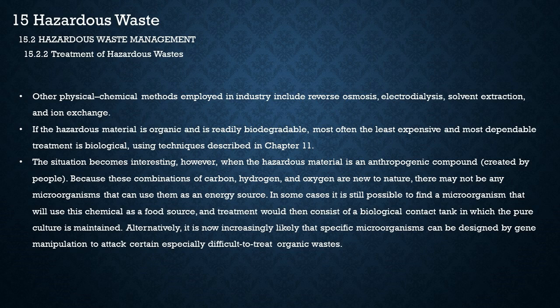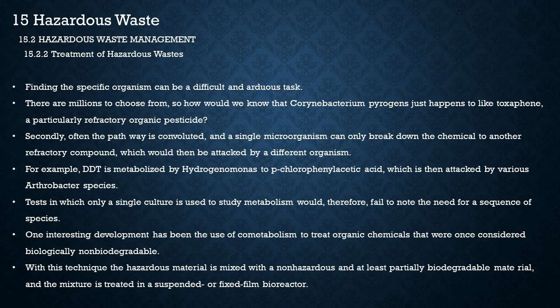The situation becomes interesting, however, when the hazardous material is an anthropogenic compound created by people. Because these combinations of carbon, hydrogen, and oxygen are new to nature, there may not be any microorganisms that can use them as an energy source. In some cases, it is still possible to find a microorganism that will use this chemical as a food source, and treatment would then consist of a biological contact tank in which the pure culture is maintained. Alternatively, it is now increasingly likely that specific microorganisms can be designed by gene manipulation to attack certain especially difficult to treat organic wastes. Finding the specific organism can be a difficult and arduous task.